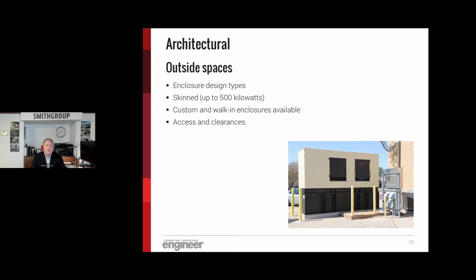When you go larger than that, usually the vendors send the generators out to custom fabricators of enclosures. Those can be walk-in enclosures that could be a compromise between indoor and outdoor. They can be custom. They can have sound attenuation on those enclosures. And even when it's located outside, you have to look at access and clearances, particularly under the NEC.